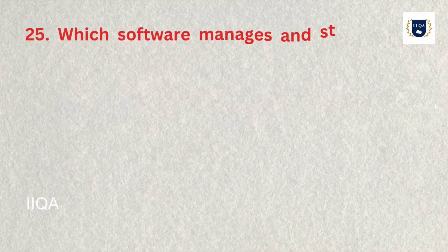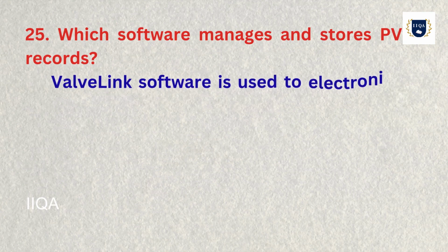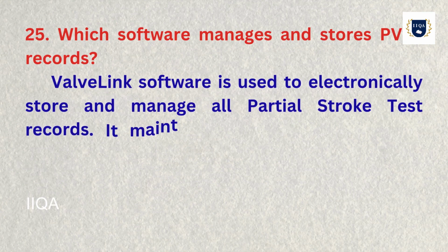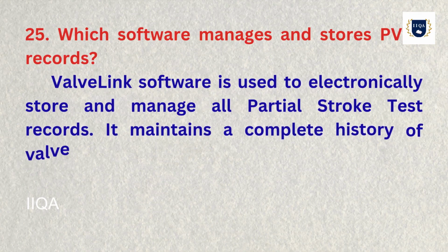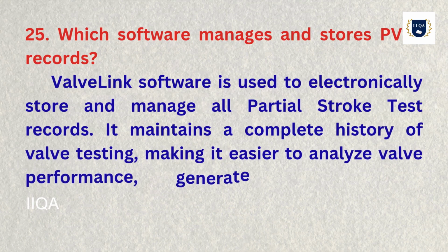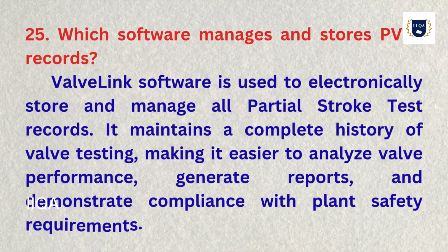25. Which software manages and stores PVST records? ValveLink software is used to electronically store and manage all partial stroke test records. It maintains a complete history of valve testing, making it easier to analyze valve performance, generate reports, and demonstrate compliance with plant safety requirements.